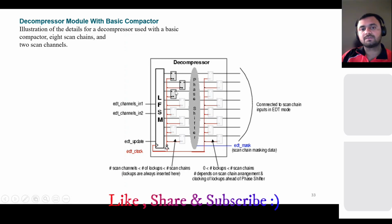Suppose you have 2 flops, flop 1 and flop 2. Flop 1 is working on the positive edge, the rising edge of the clock, and flop 2 is working on the negative edge, the falling edge of the clock. If you draw the waveform, there will be a data loss between them. To avoid that, we use the lockup latch. The tool inserts it based on that analysis.